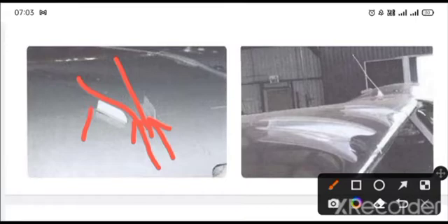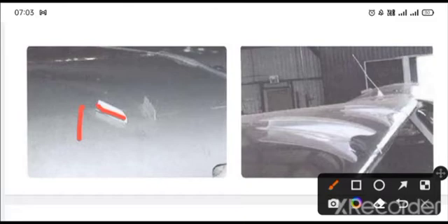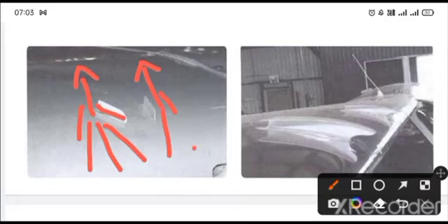So there will be this type of structure as well, and as we know, any convergent section like this increases the speed. As per Bernoulli's theorem, we know that convergent sections increase the speed. So whenever the sluggish layer comes through these small aerofoil strips, its speed will be increased and it will not leave the surface anymore. It will have more speed now, it will be energized, and it will flow over the surface very easily, like this.